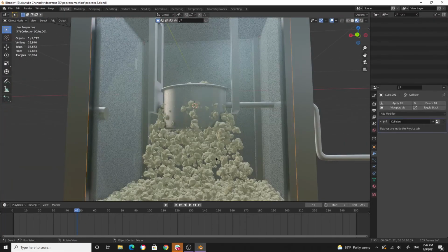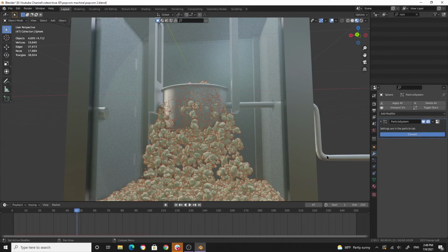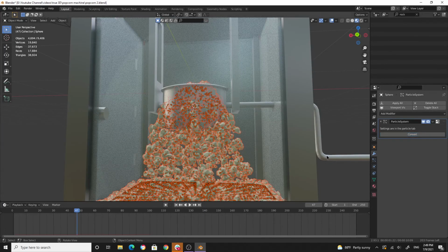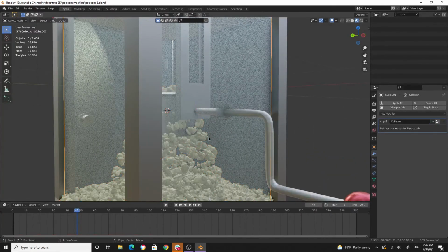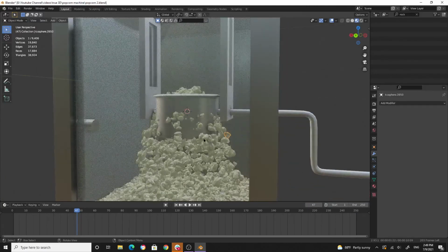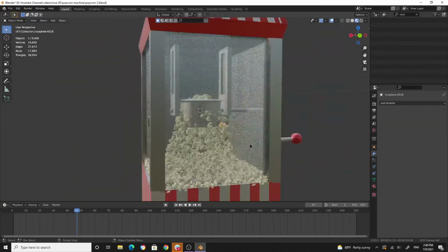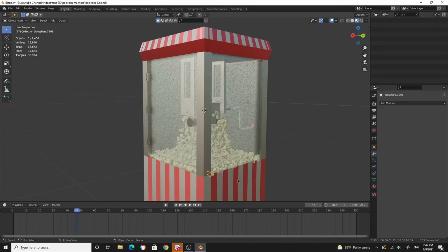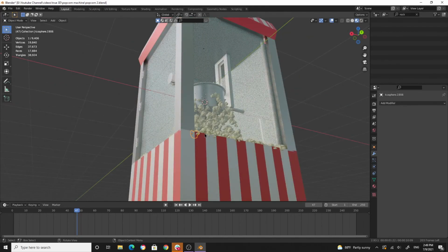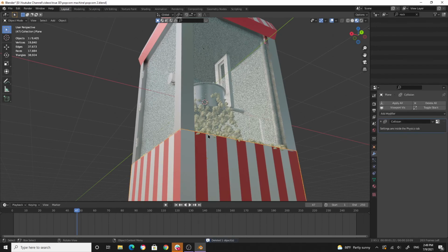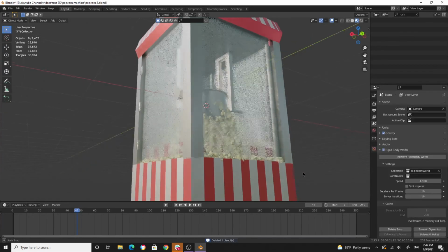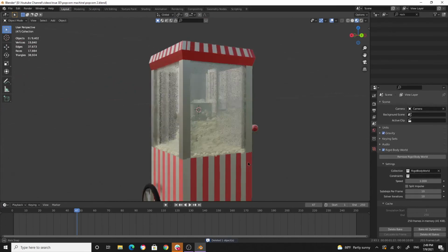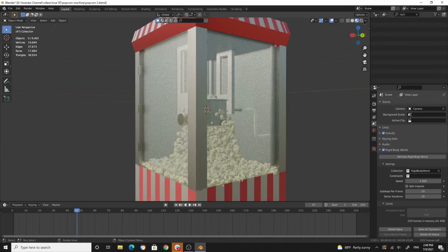Anyway, let's try that one as well, right? Convert. So this is going to convert every single piece into its own mesh. So if you click one of them, now they are separate pieces, right? See, those are separate pieces. You can adjust, or if you have some cleanup to do here, you can delete some of them, the outside stuff, right? So you can do some cleanups like this, and have a proper orientation, and then do the rendering.